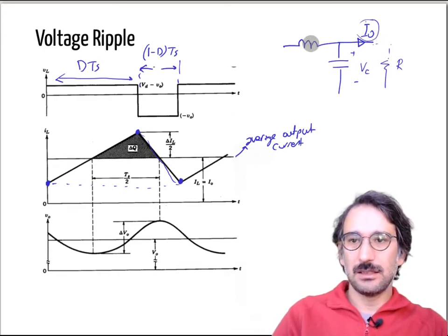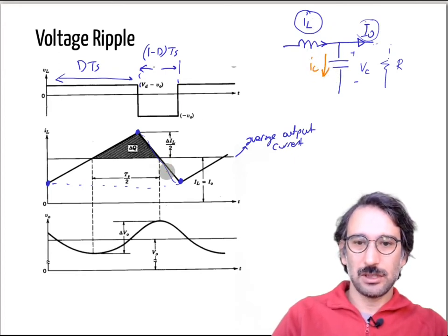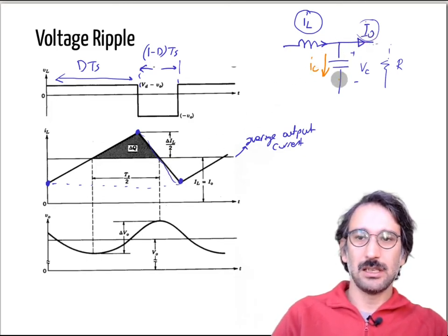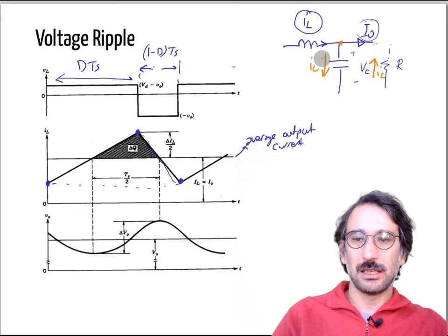Okay, so this is the DC, and then we have the inductor current coming in. So you can see whenever that current is larger than the output current, it will charge our capacitor, and whenever our inductor current is smaller than the required output current, now our capacitor will supply some current. So again, in the steady state, that voltage is going to stay constant, so the amount of charge getting in and the amount of charge getting out of the capacitor will be constant.